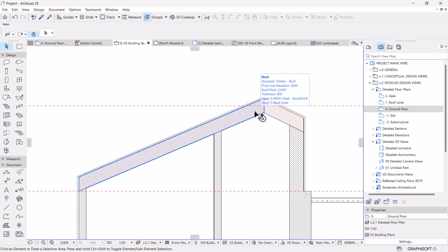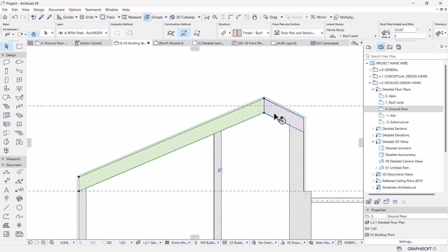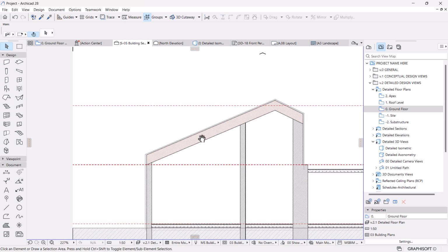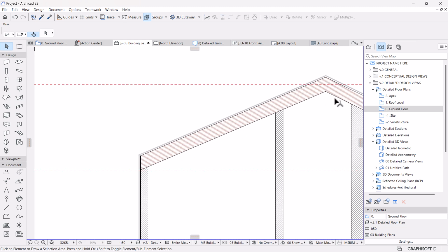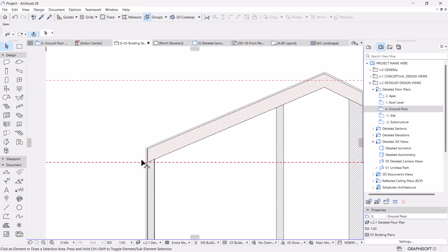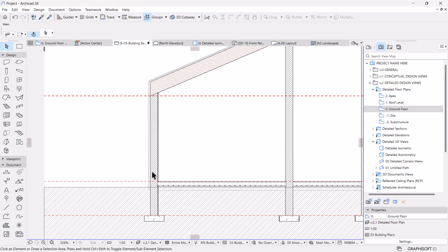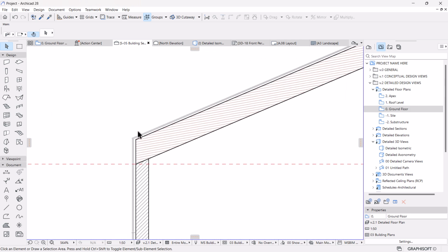We can either use the roof tool as our rafter, right? Because even the ceiling will follow this profile for our roof. So we're going to have this as our rafter, and then we place some purlines that the cladding or the roofing sheet will be installed on.